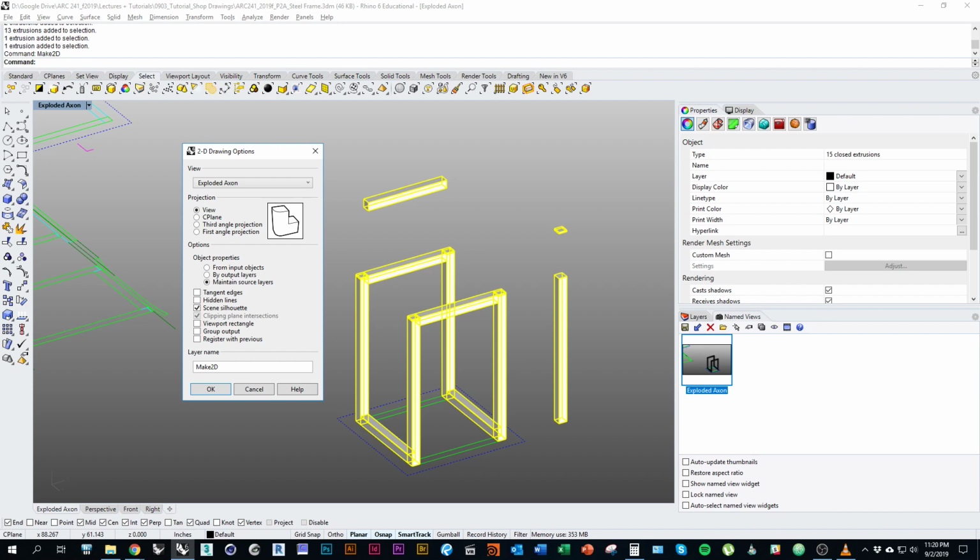And the reason that that's useful is it's going to make it a lot easier to line weight when you get to that stage. In this case, we just have one layer, so it won't make a huge difference. But the other thing we want to check is scene silhouette, and I'll show you what that'll do right now. So once those two options are set, I'll click OK.